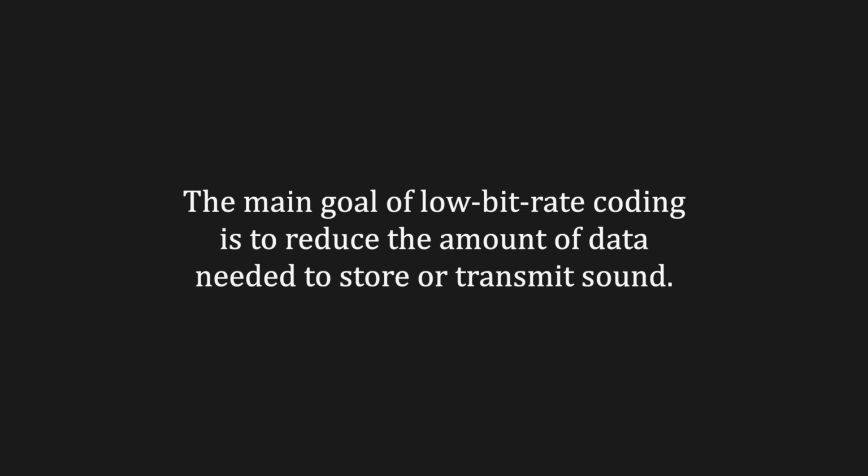The main goal of low bitrate coding is to reduce the amount of data needed to store or transmit sound. This data rate depends on both the sampling frequency and word length. Lowering the sampling frequency saves data, but also cuts off high-frequency sounds, as explained by the Nyquist theorem. Shortening the word length reduces data too, but it also decreases the dynamic range by about 6 decibels per bit